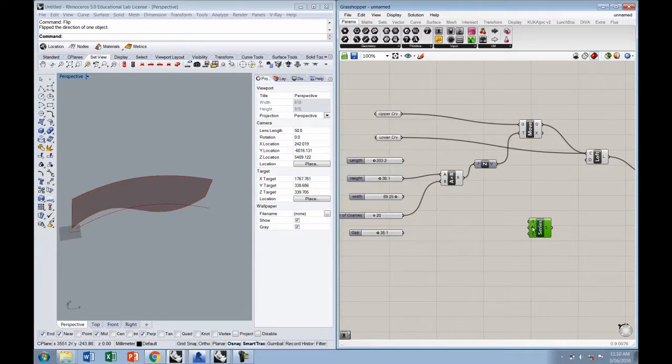If you mouse over things here, it's going to tell you what it's actually looking for in each of the different components. So if I mouse over N or C, this is the number of values in the series. That's going to be the courses. The step count is going to be 38.1, and then when I mouse over S, you're going to see here the metric values of 1.53, 4.5, so on and so forth.